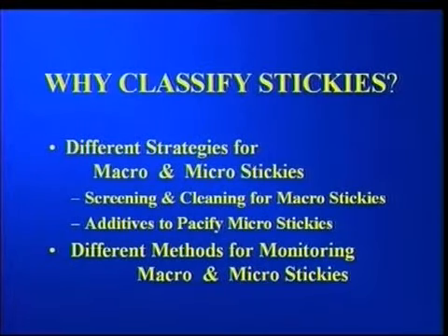Why do we want to classify stickies into macro stickies and micro stickies? The main reason is that there are different methods for measuring the concentration of macro stickies and micro stickies, and more importantly, there are different strategies for combating the problems caused by macro stickies versus micro stickies.